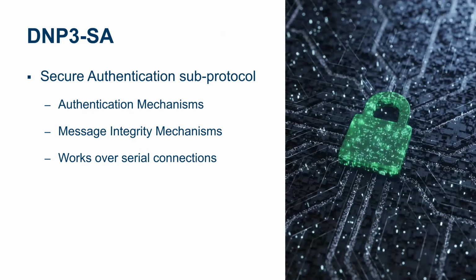It's just another layer. It adds a fair amount of complexity to the protocol. So I've not actually seen it in use, but it is a supported standardized protocol that you could implement in a device. It has some really cool features to it. It works over serial, which a lot of the encryption stuff that is built into Ethernet protocols just doesn't work on serial because it's not available. So that's one of the distinctions of the DNP3 secure authentication subprotocols. You can actually use it over these serial links as well.